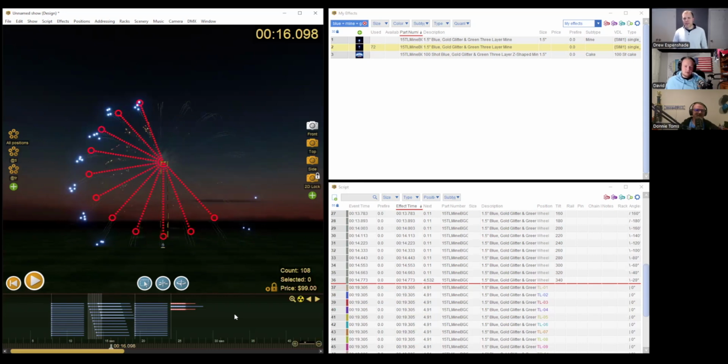Generally, the way I would do this, and I would encourage anyone who's interested: the Pyro Jam competition this year that just ended this weekend has towers and a wheel in it. The way I did that is I went on to the SketchUp 3D Warehouse and grabbed a model of a truss, a 10-foot truss stick. I brought it in, brought in another one and put it on top of that one, and built it up the way you would build, connecting truss sticks in real life.